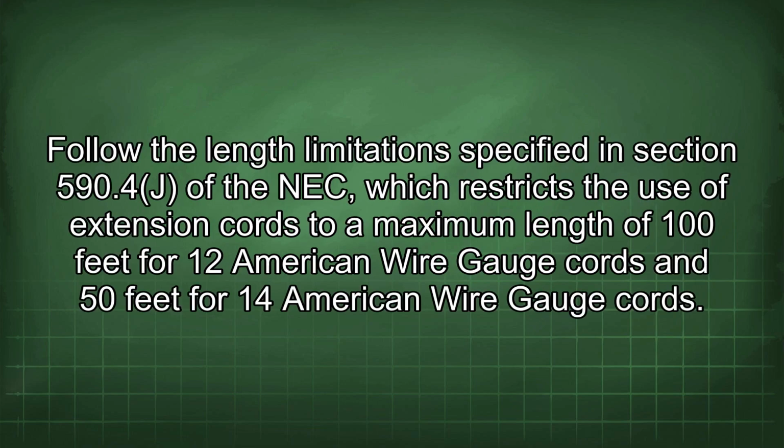Follow the length limitations specified in Section 590.4(J) of the NEC, which restricts the use of extension cords to a maximum length of 100 feet for 12 American wire gauge cords and 50 feet for 14 American wire gauge cords.